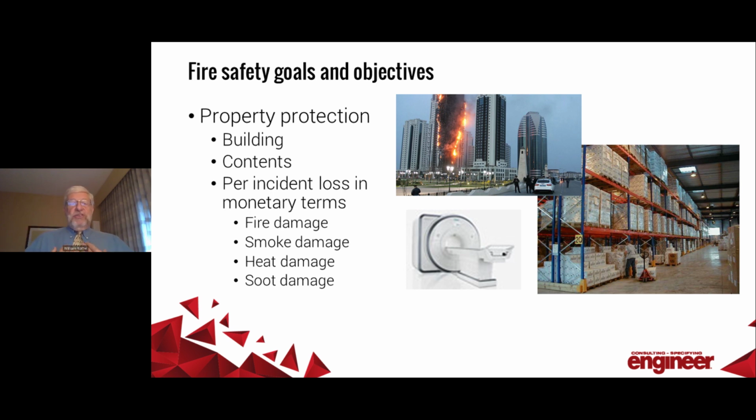Many storage occupancies are protected with a sprinkler system. The design criteria for that sprinkler system that's in NFPA 13 are based upon 3 criteria for that rack storage arrangement that we see. 1, we maintain structural stability. 2, the fire doesn't spread the length of the aisle or the row, the rack. And then 3, the fire doesn't jump across that aisle.